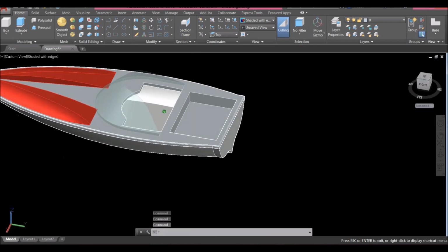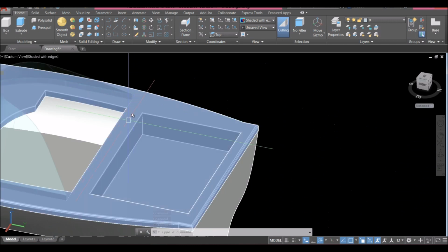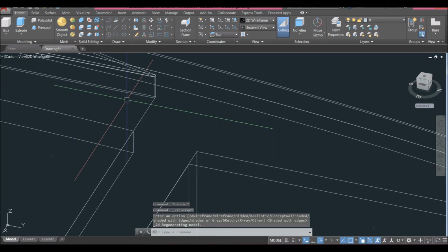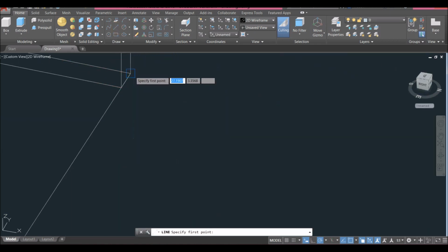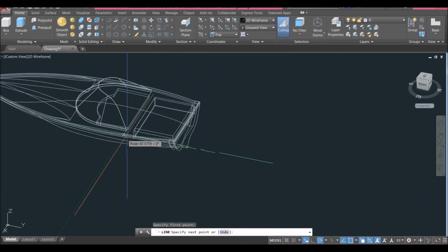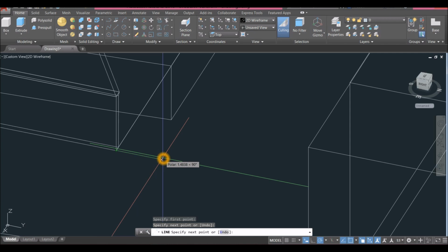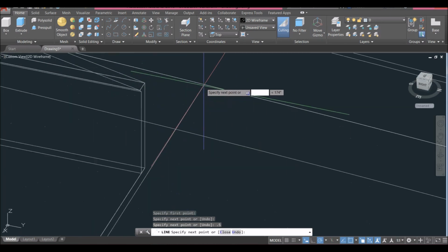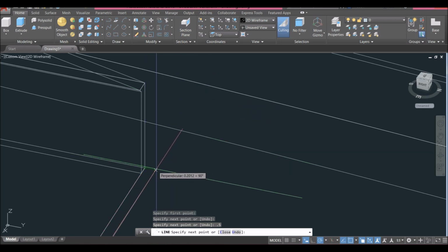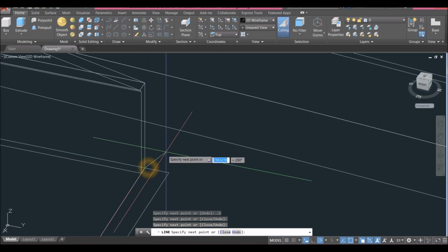So I'm going to create a glass wall first, and the height should be from this endpoint here to this endpoint. So I'm going to change this to the wireframe maybe. So I'm going to draw a line from this endpoint to this endpoint, and the thickness would be 0.5 inches, and bring this back. Just hover over, then click the endpoint.